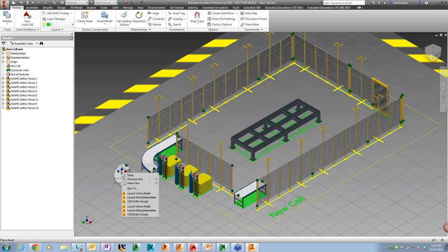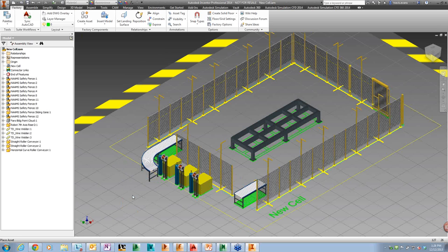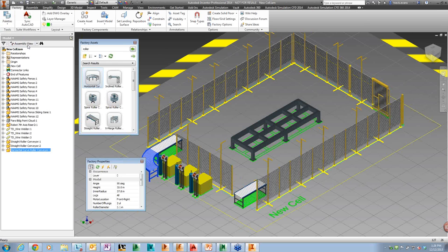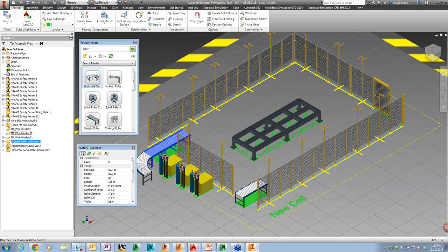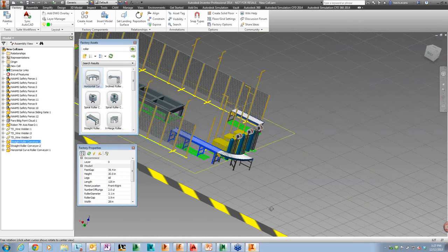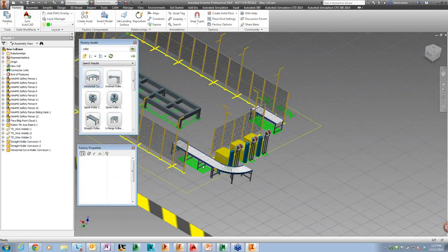And also, if I look at this process and the information that we have, pull up those tool palettes again. Let's look at some of the properties that are built inside. I have different properties that I make available. As in publishing this asset, and we'll show you how to do that, it's really slick. But if I change the length of this conveyor, and I wanted to make it 125 feet long, you can start to see how it's going to build that information up, update that model, and have some smarter functionality. Let's get a better angle on this. Here you see I've added additional supports, because it knows it's this long, it needs to add additional supports.